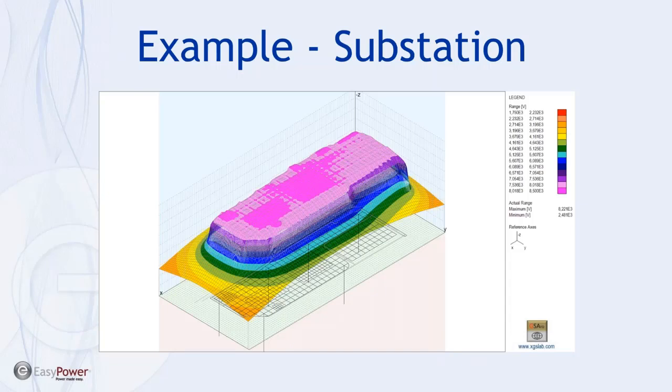And so even though the voltage is about 8,000 volts on this equipotential plane, there are minimal potential differences on the plane. If somebody is standing on this touching something, or taking a step on here, it's apparent that they're most likely safe. This isn't the diagram we use to determine safety, but it shows what the grid does, what we're building, and what happens during a fault.